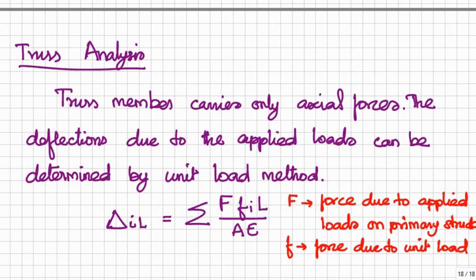The deflections due to the applied loads can be determined by the virtual work method and other methods. Many methods are there, but one of the methods is the unit load method that we follow here, so that we can get the flexibility pattern. So in general, from the unit load method, the deflection at the ith coordinate, system coordinate, due to external load is equal to summation of F small fi L